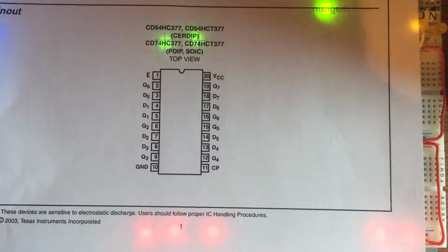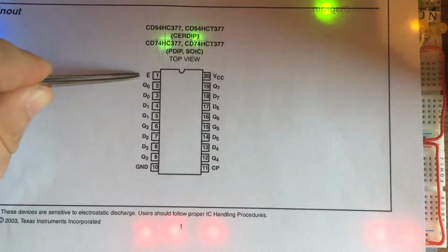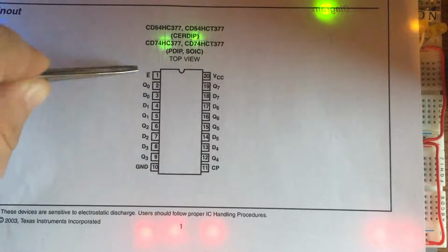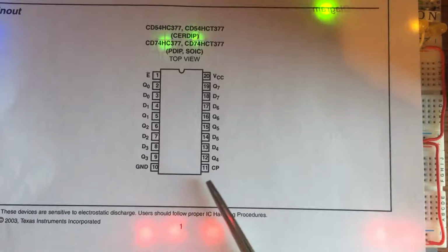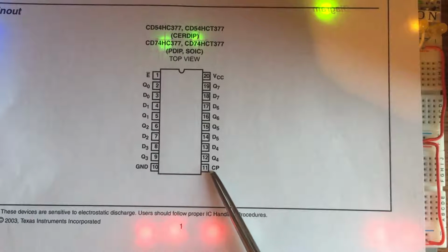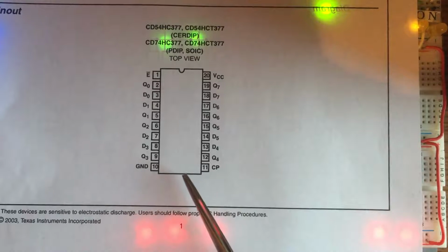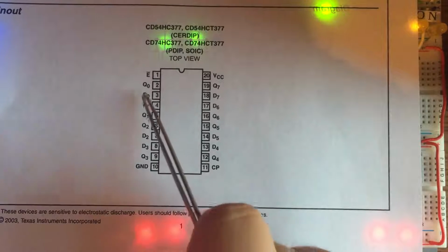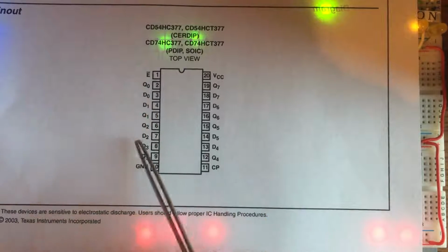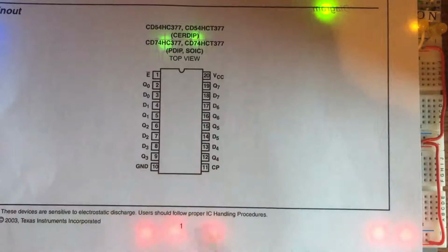So even if I were to assert this write enable signal, which in this case is active low, which means assertion means I'll pull it low, even if we were to do that, the actual write won't happen until a rising clock edge. So we're still clocking in values, which is good. But you'll notice that this chip doesn't have an output enable. So its Q output signals are always enabled, no matter what's happening.